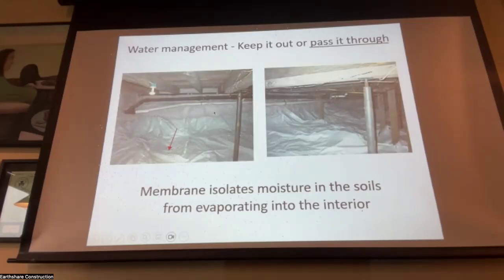These are examples of crawl spaces that I did 100 years ago, but this is above the seasonal high water table, and the plastic goes up maybe a foot below the top of the stone, because the grade is right there. So the plastic goes up behind the spray foam. The spray foam starts at the other side of the floor and goes down onto the vapor retarder.